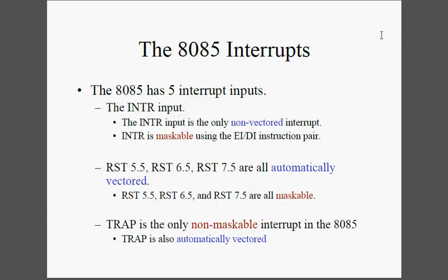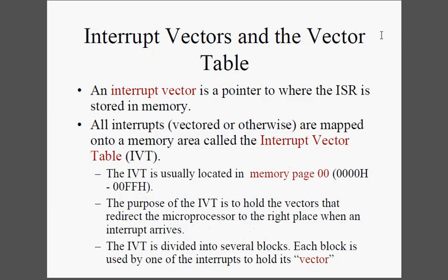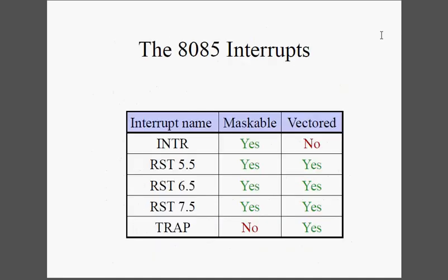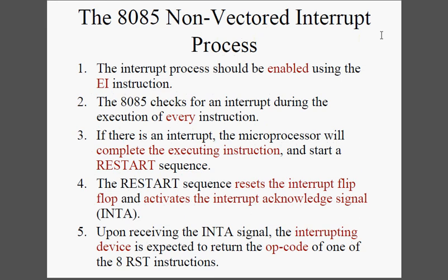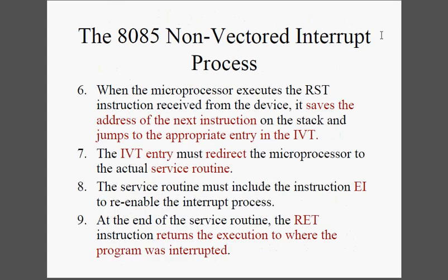Interrupts is also the same, and for interrupts you can refer to the online lecture I've already made. For interrupts, the most important thing is first to know the types of interrupt. The second is the interrupt process, what happens when the interrupt pin is high. Step by step, you have to know how the processor reacts to the interrupt. The last one is how to write the code to trigger or to service the interrupt.